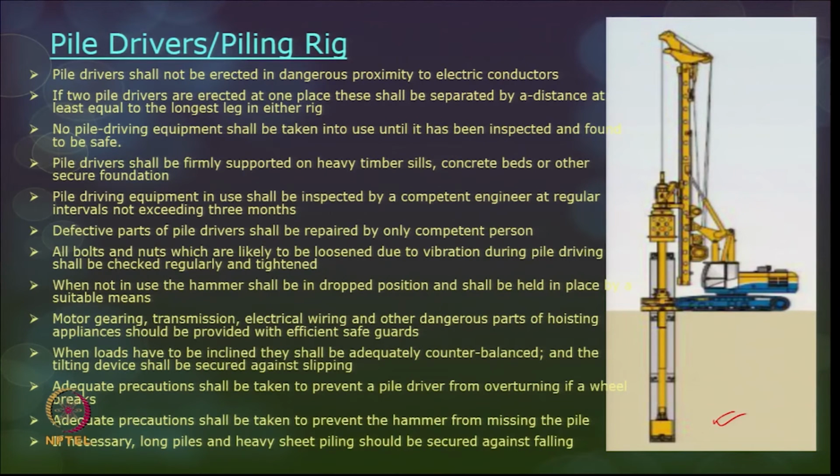No pile driving equipment shall be taken into use unless it is inspected and certified that it is safe for use. The pile drivers shall be firmly supported on heavy timber sills or concrete beds, so that there is a proper stable foundation. And the pile driving equipment in use shall be inspected by a competent engineer at regular intervals, not more than 3 months.